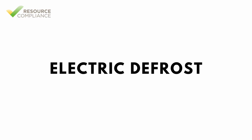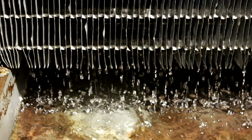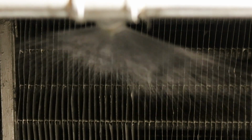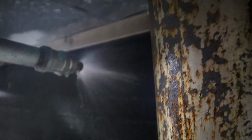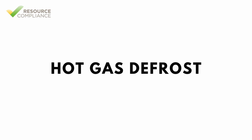Electric defrost consists of tracing the tubes and pan with electric heaters that, when activated, will cause the frost to melt and collect in the drain pan. This method is commonly used in halocarbon systems. Water defrost is accomplished by spraying ambient temperature water over the surface of the coil, which causes any ice to melt. When water defrost is used, it is important that the coil be allowed to drip for an extended period of time after defrost, before turning the evaporator back on. If the evaporator is turned on too soon, water on the surface of the coil may freeze, rendering the defrost pointless. Hot gas defrost is the most common defrost technique used.